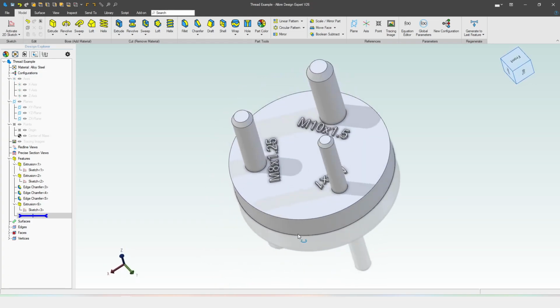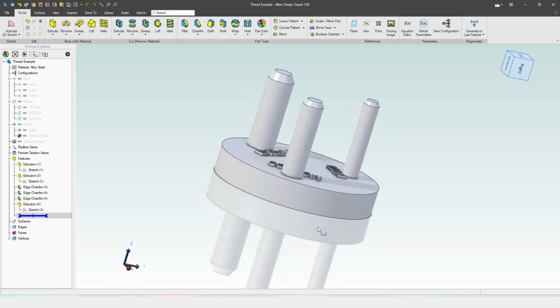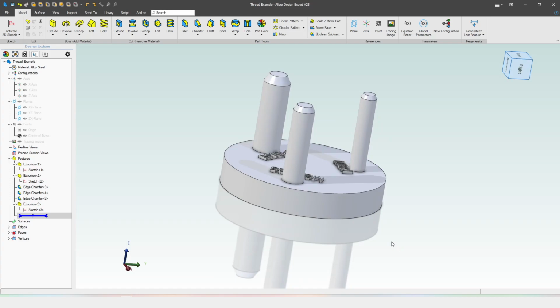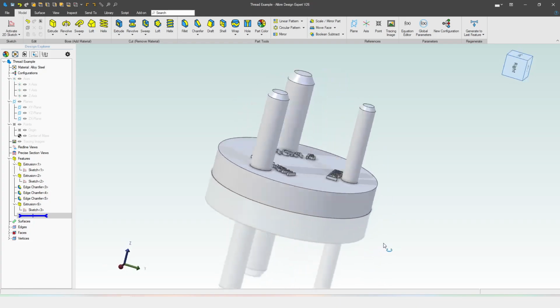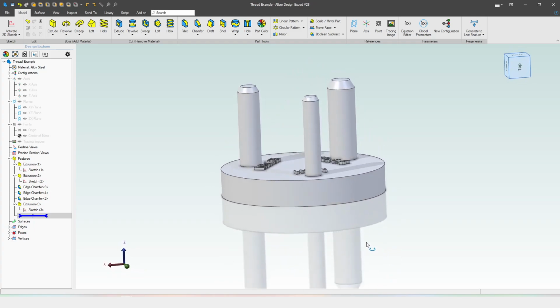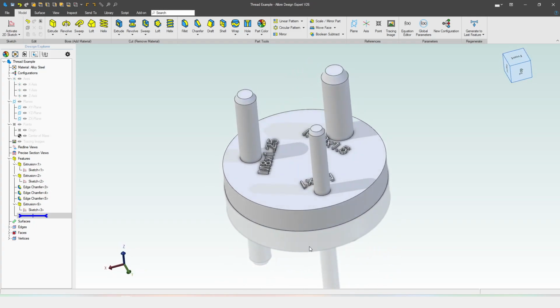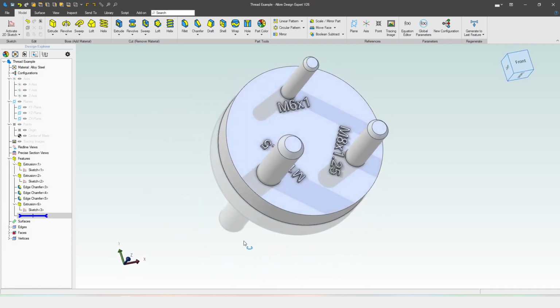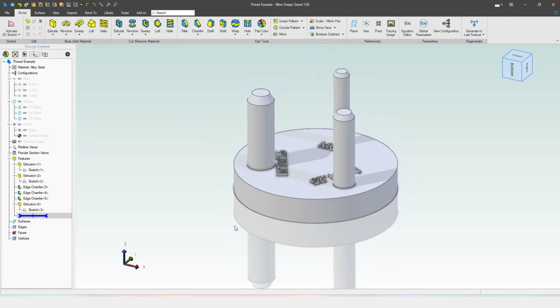Now, what are we going to be doing? Well, Alibre cannot do threaded forms for 3D printing, right? Where you actually need the external thread to be there. It doesn't have a tool for it, but we could make a tool for ourselves, right? And we can make it quick and efficient and nice and all of that. So first I'll show you how I'm going to make these three threads on these three poles.